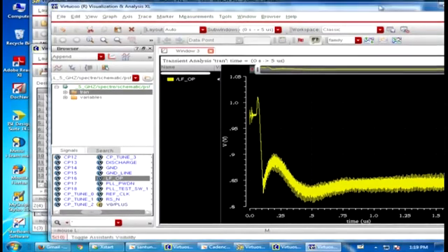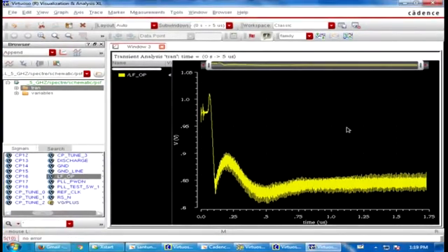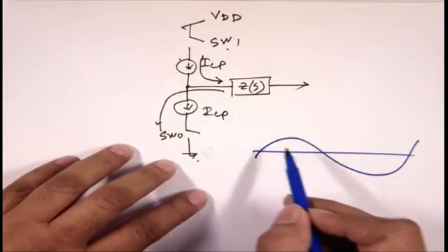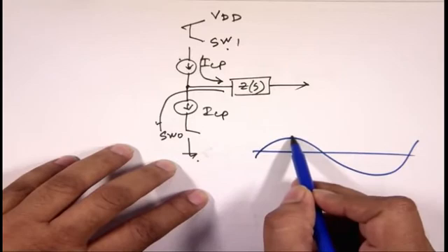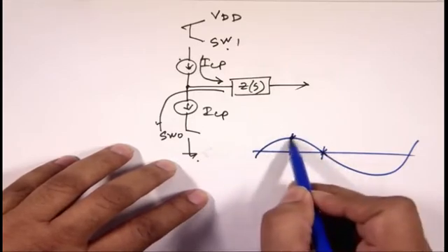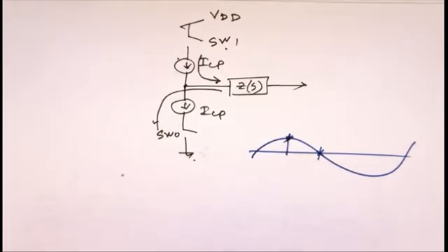So what I am saying is, suppose you have this kind of sinusoidal signal, and now if a noise occurred here and if a noise occurred here, which will be more vulnerable? These are important concepts, right? Use your common sense. When it is at the zero crossing, that will be more vulnerable and we will have more jitter.